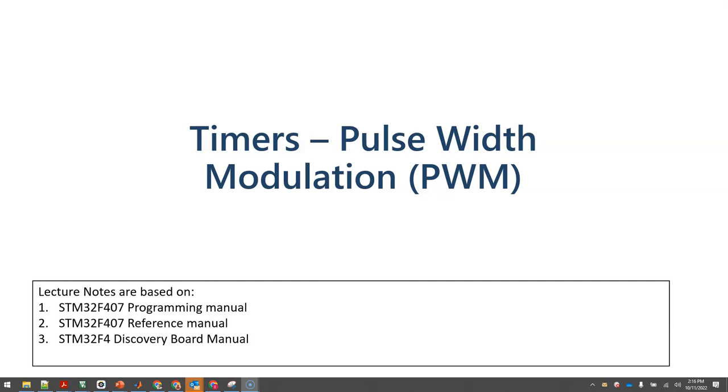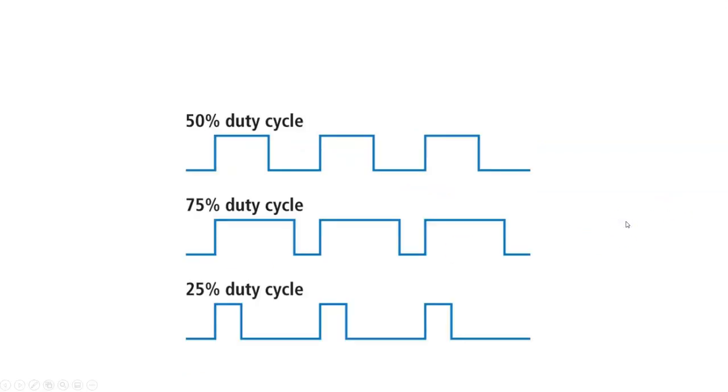So pulse width modulation, what does that mean? If anybody's ever used an Arduino, and I remember quite a few of you said you had at one point, there is an Arduino function called analogWrite. If you really look at the analogWrite output on an oscilloscope from the Arduino, you don't really get an analog value. What you get is a digital waveform which goes high and low, and the analog voltage is proportional to the amount of time that waveform stays high with respect to the overall period of that waveform.